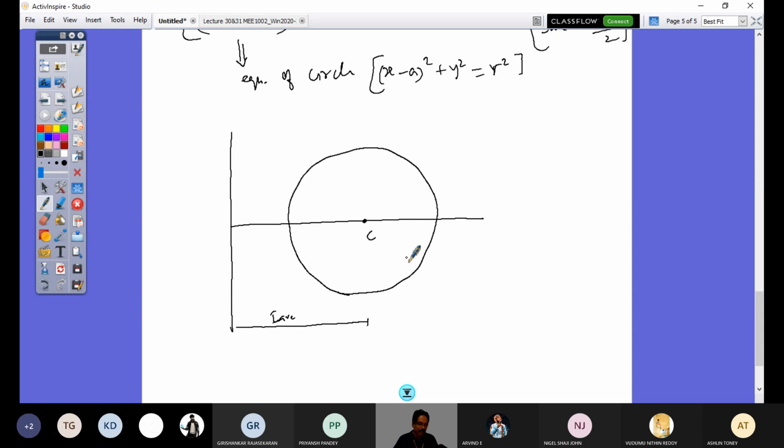Now I can represent coordinate M here with Ix dash and Ix dash y dash. That means what? On my horizontal axis I would take Ix dash, Iy dash, and so on. On my vertical axis, I will take Ix dash y dash, above positive, below negative. So product of inertia is on the vertical axis, and area moment of inertia on the horizontal axis.